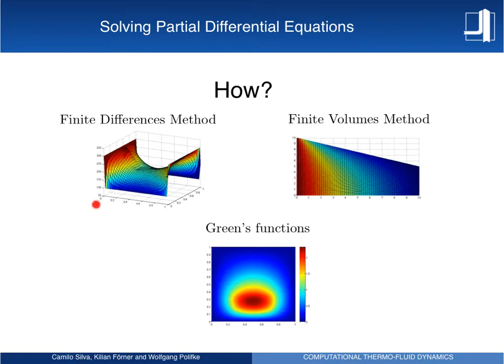Today we will, for the first time, start with the numerical discretization of an actual partial differential equation. And we will start with one of the most useful and most simple PDEs, which is the heat equation. To give it a little touch, which is a little bit nicer, more fun, we have a conductivity inside the heat equation which is not uniform. So you will see here, for example, that the isolines of temperature at some point get deviated because you have a solid inside with a different conductivity.